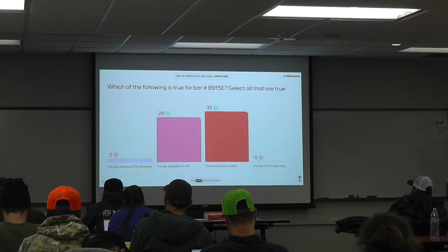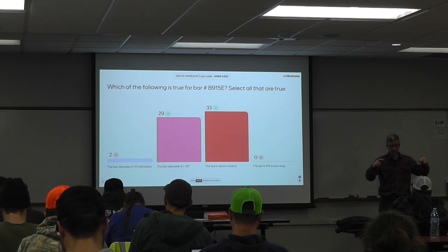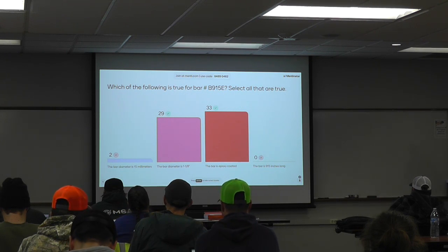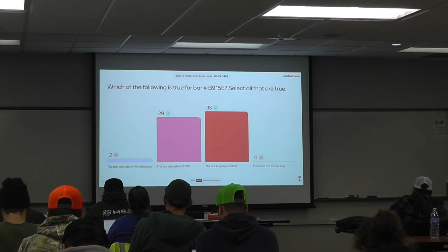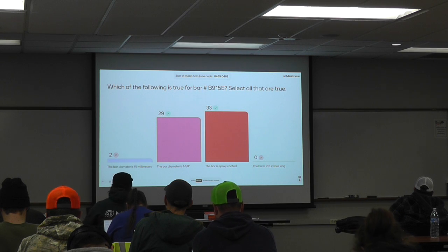And then the length of bar splices is on page 552, if there's nothing in the plan. The way that bar splices work is, if there's something in the plan, that would govern. But if there's not, you would use this table on page 552 to see what it would be. So it's number of bar diameters. But as far as the weight of the bar and the diameter of the bar, it is shown on page 553 of the table.